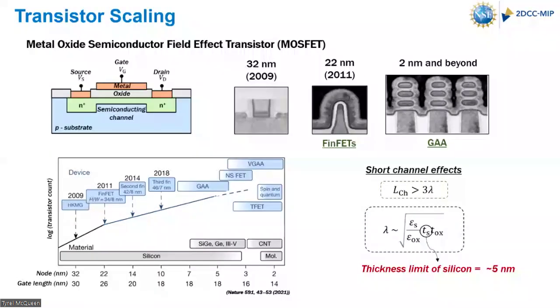So the field switched to hafnium dioxide, to high K dielectrics, all to get around this problem with short channel effects. And that kind of took us through. So this is like the happy physical scaling region, which occurred maybe up until 2010, right?